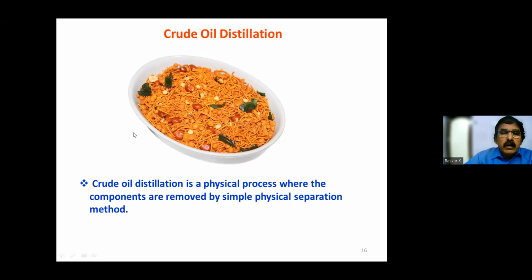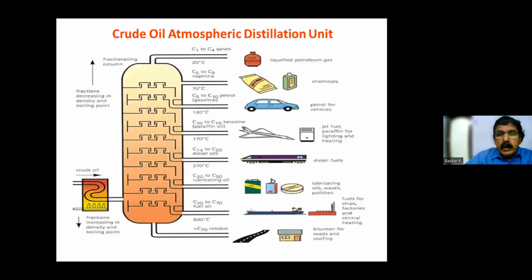Right? Now we'll go to the distillation tower. Okay, now slowly watch my cursor. The crude oil, after treating, because crude oil will have some salt, the salt will be removed through a desalter. We have a desalter in between. After the desalter, where the crude is free from salt, it will be fed to the crude oil preheater. We have a preheater here. Then it enters the distillation tower. This is a distillation tower, a huge tower. You can see that.